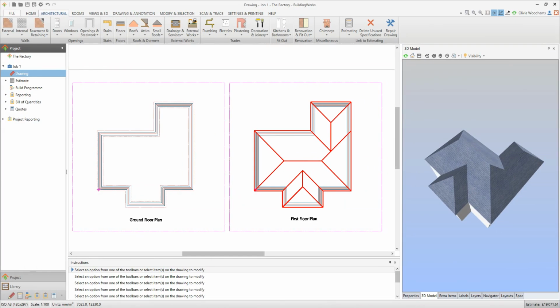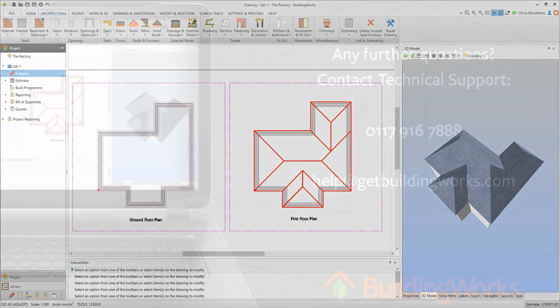Over to you. Draw the external walls of the existing property, ensuring you select the existing specification in the Wall Component Builder. Then go to the Roofs drop-down menu and select the Roof Refurbishment option. Select a roof specification based on the tile type and then click Review Specification. Work your way down the list of assemblies, setting the percentage replacement or reuse as needed for your job. Check the pitch and other dimensions of the roof, then draw it, following the on-screen instructions. Finally, add any additional costs for each section of roof using the Extra Items window.